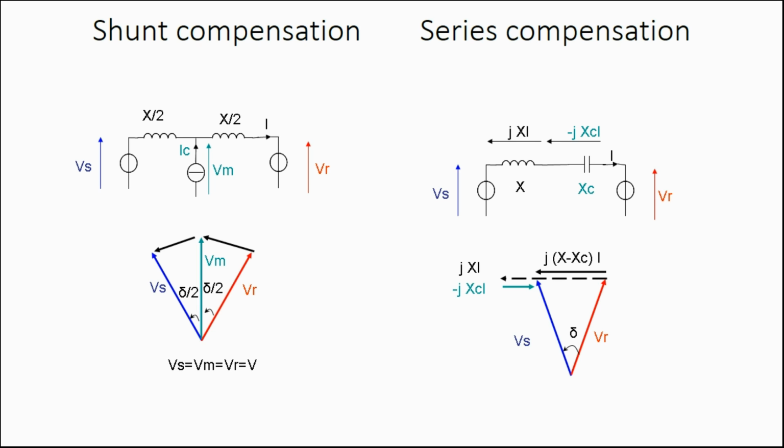Shunt inductive compensation. This method is used either when charging the transmission line, or when there is very low load at the receiving end. Due to very low, or no load, very low current flows through the transmission line. Shunt capacitance in the transmission line causes voltage amplification, the Ferranti effect. The receiving end voltage may become double the sending end voltage, generally in case of very long transmission lines. To compensate, shunt inductors are connected across the transmission line.